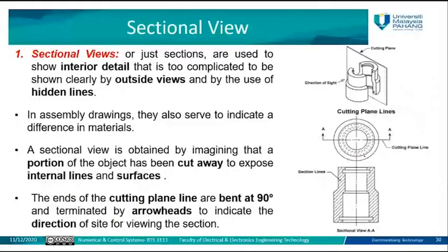This view we call the cross or sectional view. If this is the top view of the object, it will be a circle. There are two circles, and another represented by another circle: one circle, two circles, three circles. This is only the top view that you have. But when you cut this using a cutting plane, you have more information about the thickness, how it looks inside, what the diameter of this part is, of the next part, of the third part, and so on. So more information is extracted in the sectional view.